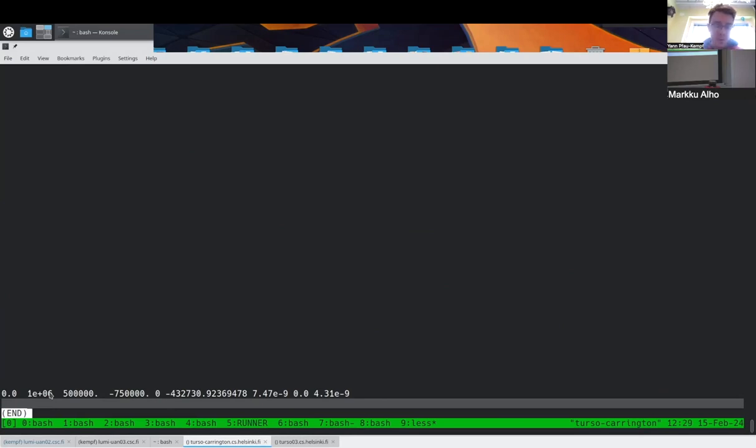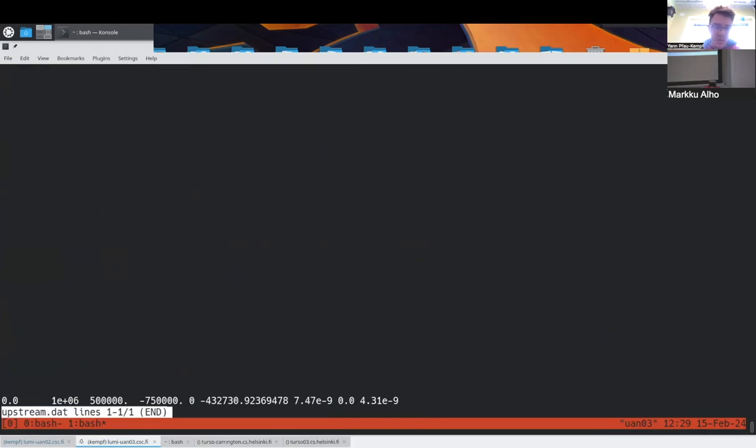So this file, if you go to setting up a time dynamic upstream boundary, that's a bit advanced and a very recent thing. We only included that in the course of the last year. It will read these lines consecutively, and the first value is the time. So if you put 0 and 10, it will linearly interpolate the state of your boundary condition between the times of 0 and 10. The algorithm is a bit dumb in the sense that it just looks at the file, looks how many lines the file has, and reads them in sequence. That's why it was complaining, because it read the second line, but it was empty. Okay. And if you compare now to this, it has no further line. It just says there's one line.